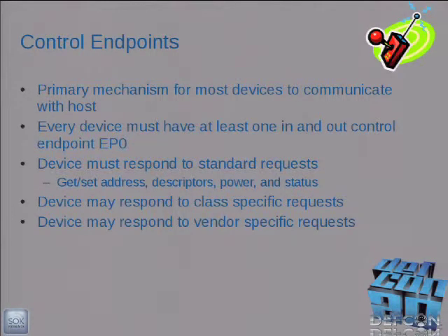All right, so control endpoints. Most devices use this to communicate with the host, and every device has to have at least one. We call it endpoint 0, not endpoint 1, because we don't program in BASIC. And the devices must respond to standard requests. These standard requests are things like, set your address, give me descriptors, change your power settings, and what's your status anyway? Some of you may have gotten status input from your badges.